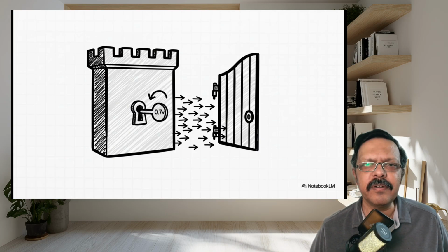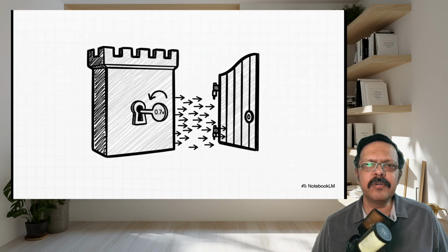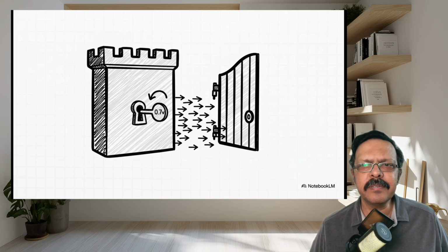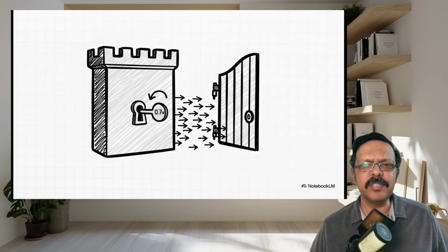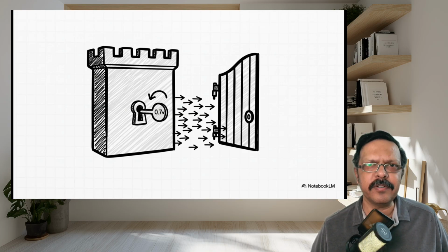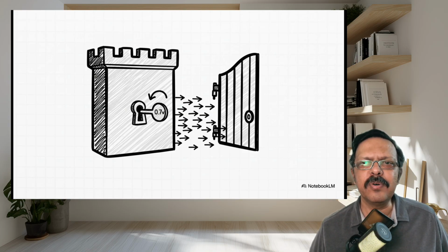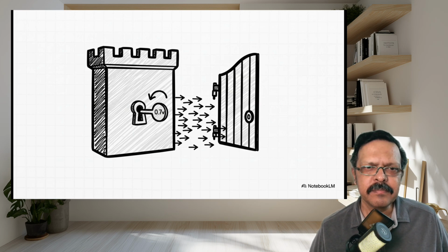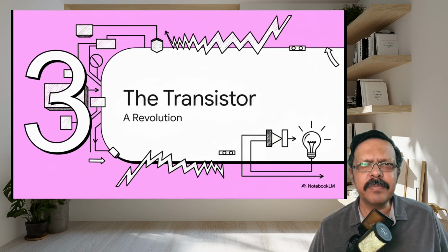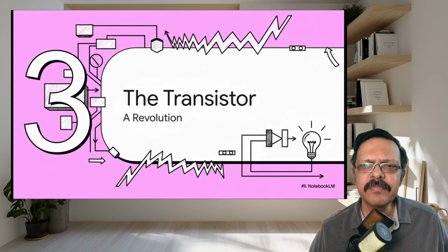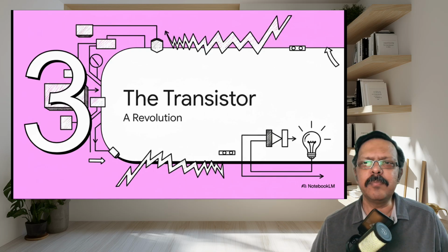And as with all silicon diodes, you need about 0.7 volts of forward bias before electrons finally have enough energy to cross the junction and let the current flow. That's why the diode works and why the PN junction is one of the most important inventions in electronics, because it controls the flow of electricity. But the diode can only enforce direction. To control current, amplify the signal or act like a switch, we need something a little more evolved. So let's look at that little more evolved component.